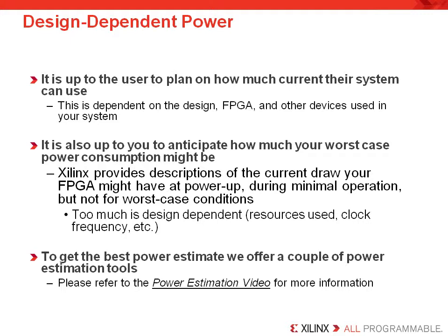Now we provide descriptions of the current draw your FPGA might have at power up or during minimal operation, but we don't provide information on worst case conditions. Simply put, too much is design dependent. That is dependent on the resources used, the clock frequency you run on, etc.